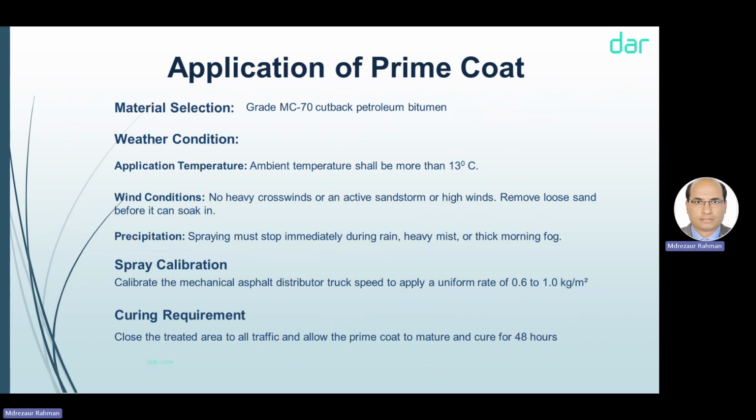And for the approved supplier, we have to check the temperature, which must not be 13 or less. It should be more than 13. Wind condition: there should not be heavy wind. There is no sandstorm; during a sandstorm we cannot do it. No high wind speed. Precipitation: there is no raining. Even small drizzling, we cannot do it.